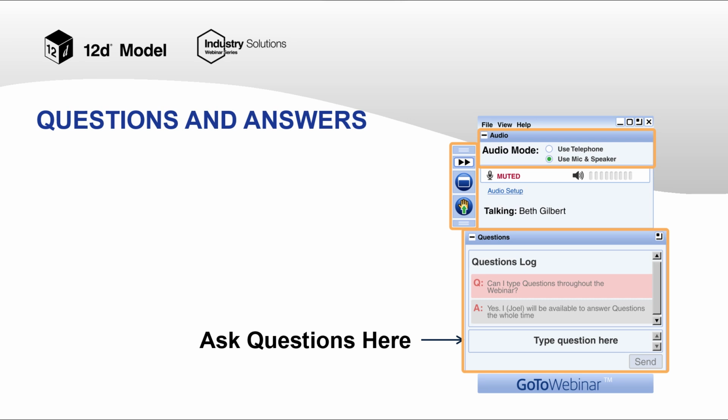Good question. So requirements are you need to have version 15, CU1K and above, and your license needs to be under maintenance. And if you're wanting to trace things into Trimble spreadsheet and stuff, you will need to have survey. And if you're a Kiwi, you need the LINZ XML module as well, just to make the whole comprehensive thing work. But as a minimum, license needs to be under maintenance, and it's version 15.